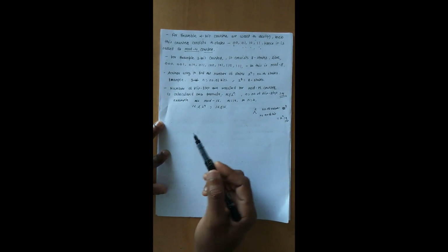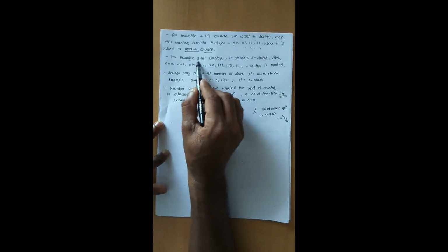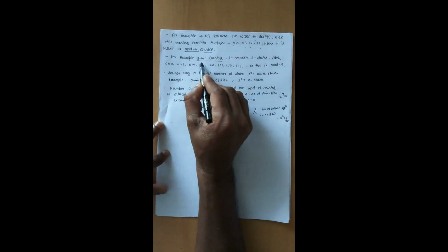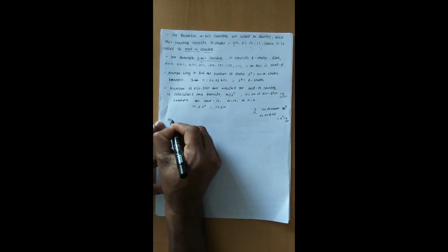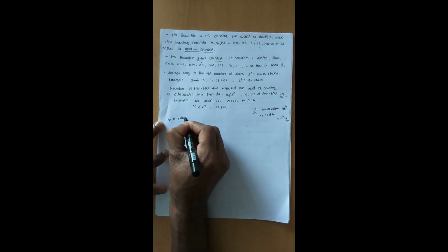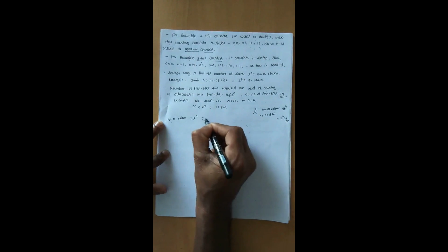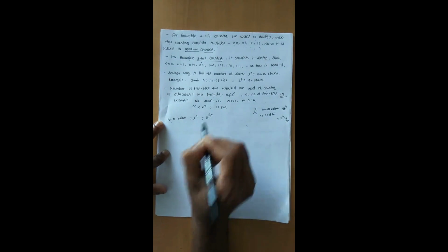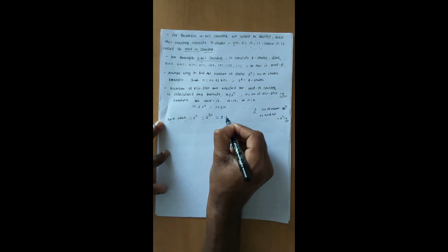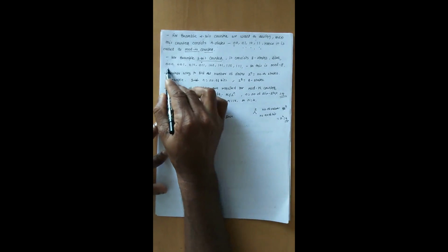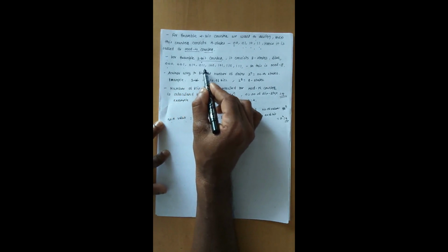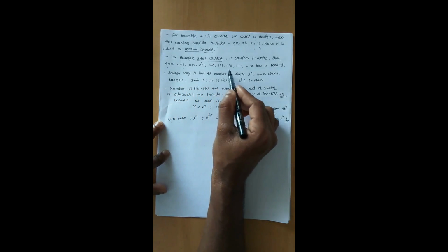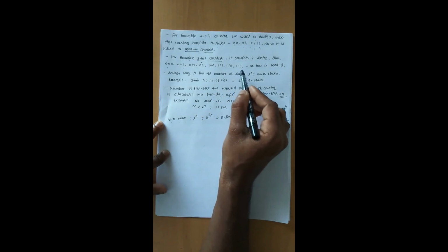In a similar way, we will take another example, in which we implement a 3-bit counter. The number of values is equal to 2 raised to n, where n is equal to 3, because the number of bits is 3, so it produces 8 different states, and these are 000, 001, 010, 011, 100, 101, 110 and 111.